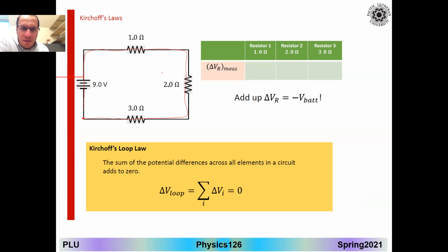So for simplicity, let's assume they are series connections. Let's assume the current here equals 1.5 amps, just for simplicity. Again, to find the summation in the loop, the closed path, we need to add the voltage in each element: the voltage source and the 3 resistors.